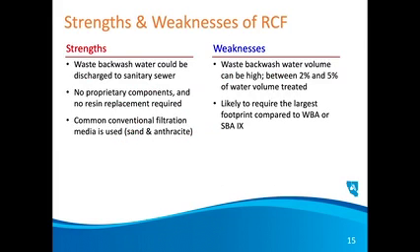The good thing about it is that this backwash water is low enough in salt or in chromium that you can discharge it, and many sanitary sewers would accept it. In fact, it might be a little too dilute for some wastewater agencies that need you to reduce the volume, just because it's too dilute for their wastewater plants. There's no proprietary components to it if you're using ferrous as a reducing agent, and it's a common conventional filtration process that many operations staff are familiar with. It does generate a significant amount of waste backwash water, 2 to 5% probably, and is likely to require the largest footprint compared to the other processes.